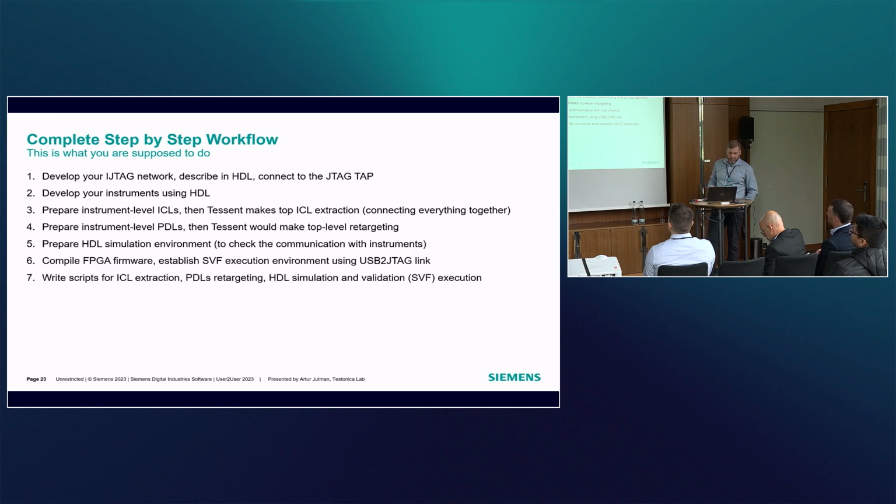So if we look at the step-by-step workflow, first you need to develop your IJTAG network, describe it in HDL, and then connect it to the JTAG test access port on the FPGA. You need to develop your instruments using HDL. You need to prepare instrument-level ICLs and instrument-level PDLs.